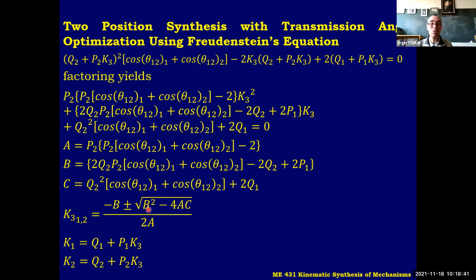We may need to iterate, and definitely we have to check our kinematic design for kinematic acceptance. If it's acceptable kinematically, you can proceed, you can perform force analysis, you can start designing the links, bearings physically, etc., which is not my topic. Even this much is too much. But you have to do all those checks, okay?